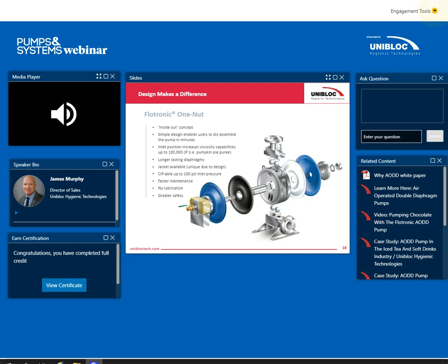But as the pump is cycling much faster, the peaks become much more condensed, and so the pulsation is less noticeable. I'd also say the thicker the product, the less pulsation; the more water-like the product, the more pulsation you'll see. So the best case scenario for reducing pulsation is either a pulsation dampener, or run the pump at a pretty quick speed with a very viscous product.